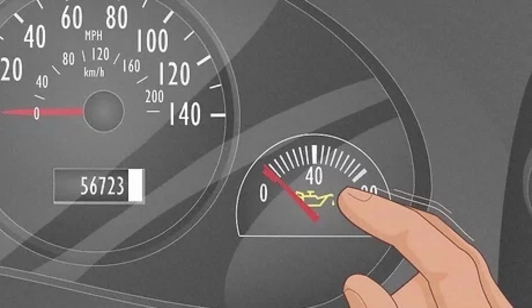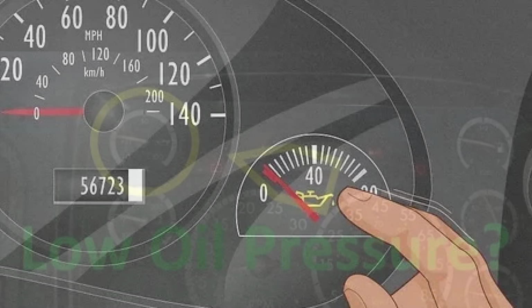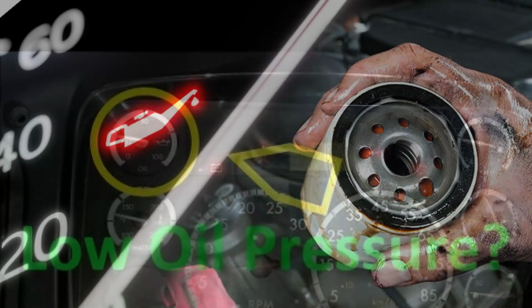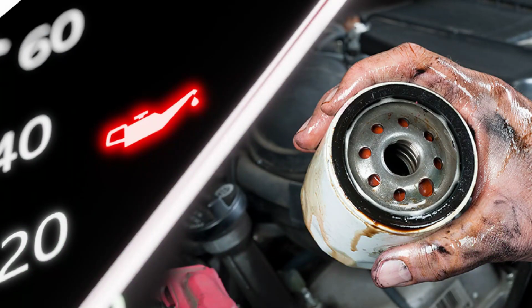There are several possible causes of the P0522 fault code, including faulty engine oil pressure sensor. The sensor itself may be malfunctioning and sending incorrect readings to the ECU. Low engine oil level. If the engine oil level is low, the sensor may not be able to detect enough pressure. Dirty or clogged engine oil filter. A dirty or clogged filter can restrict oil flow to the sensor, causing a false low pressure reading. Electrical problems. There may be a problem with the wiring or connectors to the sensor, causing an interruption in the signal. Faulty engine oil pressure regulator. The regulator may be malfunctioning and not maintaining the correct oil pressure.